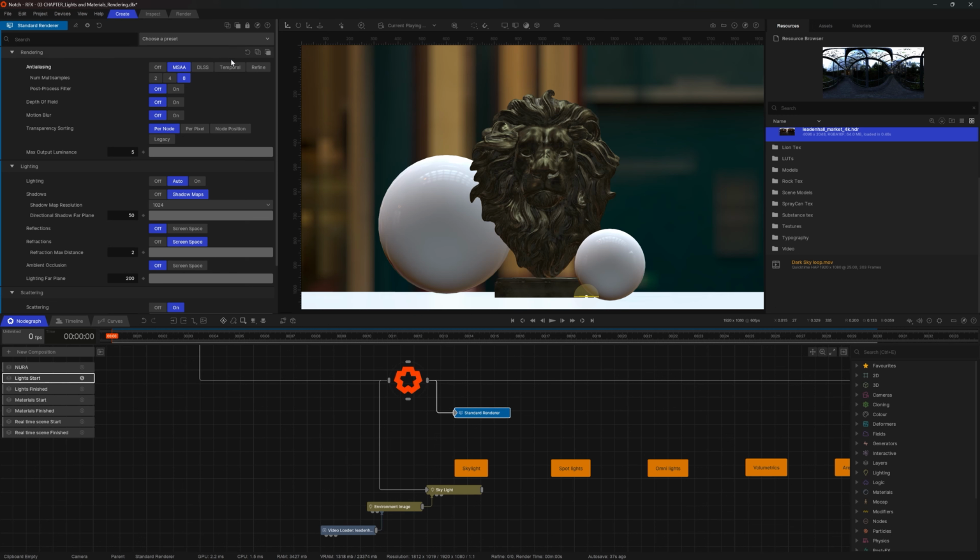And now let's just go through most important properties of the actual renderer. First of all, we can look into anti-aliasing. So we have an option to turn it on completely, or we can use the default MSAA. This anti-aliasing option samples geometry 2, 4, or 8 times to reduce aliasing on geometry in the scene. So it will slow down if there's a lot of geometry in the view. So just keep that in mind. And as stated, you can tweak it to less samples if you choose so. But the default 8 is rather good in my opinion.